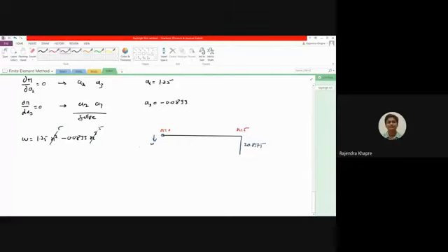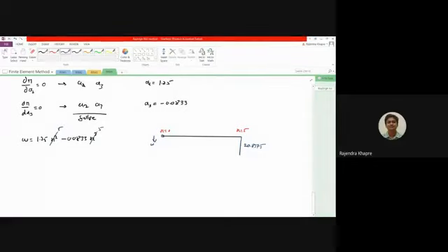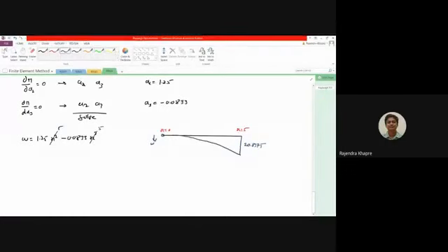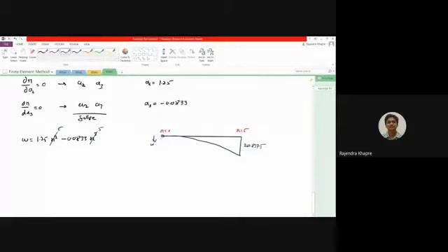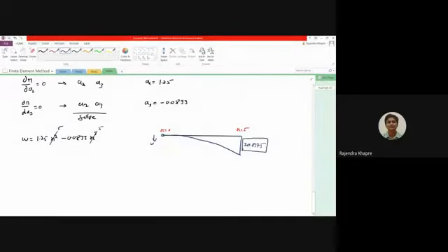This is a third degree polynomial because the x cube term is there, so all we have to do is join this like this. Ideally, whenever you see a cantilever beam it should deflect in this pattern only, and if you solve the problem using any software you should get this value, that is 20 point something, because I solved this problem in STAAD and got this value. The same value I have obtained over here.